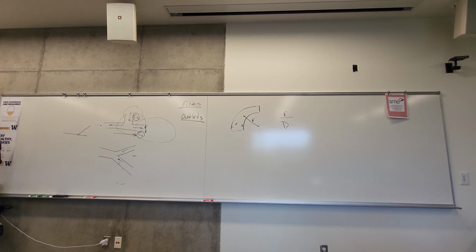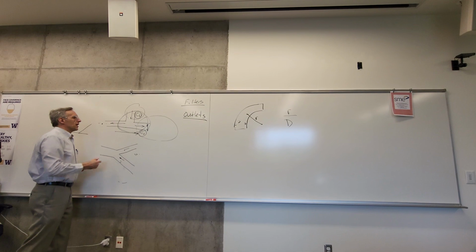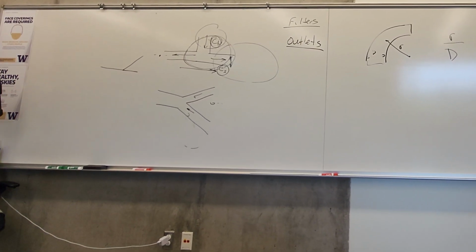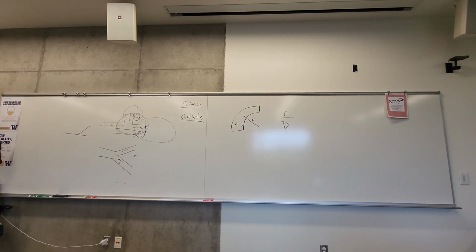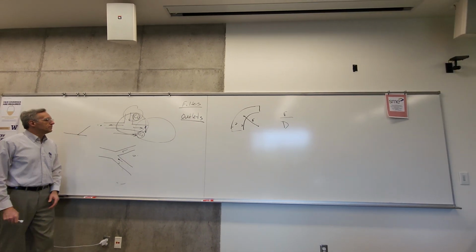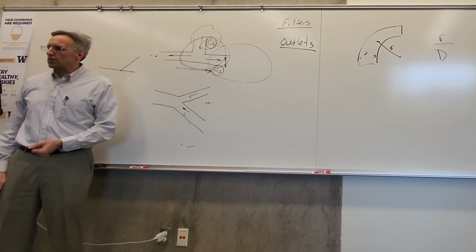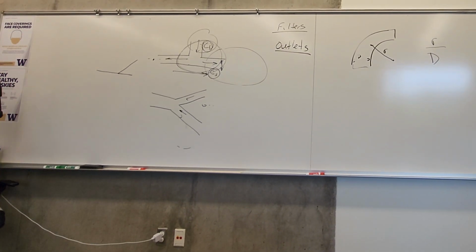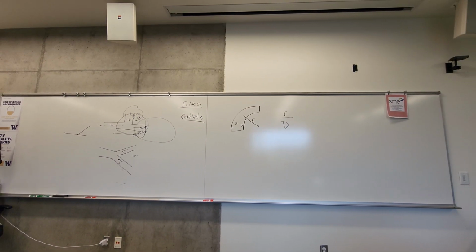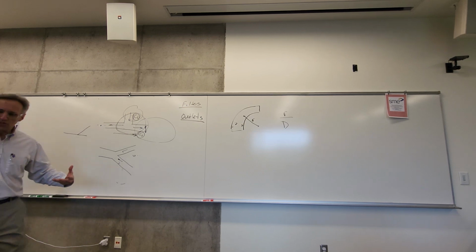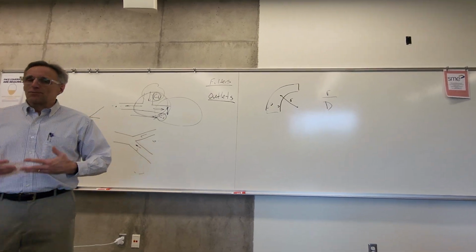But I really, I mean, using equivalent length, I shouldn't have done that. I was trying to find a way to ease the load of working with the losses and fittings, and getting back to an approach that I used to use a long time ago. And it didn't even tell you what the dimensions were. Somebody asked me, are those equivalent length tables in inches or feet? What's the unit of the equivalent length? And I went and looked at it. God, there's no unit listed. And of course it's feet, but this is part of the problem in HVAC, there's just all these assumptions about units.